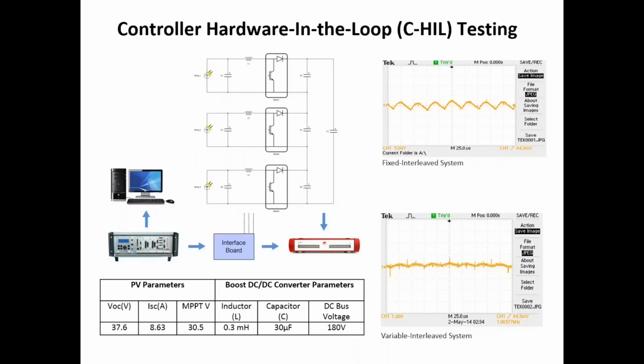So I think we are back to the same exact kind of scenario out here: if you are deploying something in the field, like a UPS system or a microgrid, you can't predict everything that you would see in the field. You can't predict all the fault modes. And so it will pay to actually have a simulation or emulation, hardware-in-the-loop kind of system where you could fall back during your commissioning of the real system, such that you make sure that all your controllers work. And that's an invaluable thing.